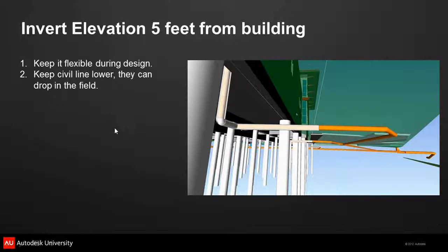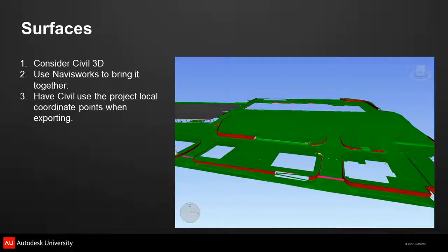The civil engineer should write an action recorder that will do 4 movements on that civil file. They should apply a Z rotation, and they should apply the X, Y, and Z translations so that the civil file utilities are delivered on the project's coordinates. We talked about setting up project coordinates. I prefer to do all plumbing coordination on a local project coordinate and not true north. The whole design team around plumbing is thinking true north. I've seen a lot of mess when people try to do the coordination on state plane. We can talk about that in the Q&A if people have different perspectives on that.